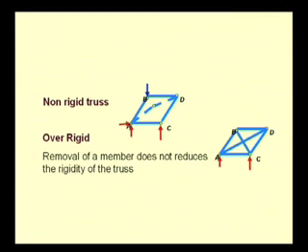In order to optimally design a truss, we have to design trusses which are just rigid. That means a sufficient number of degrees of freedom have been arrested and we do not have additional members which, if we see in terms of economics, is not viable.